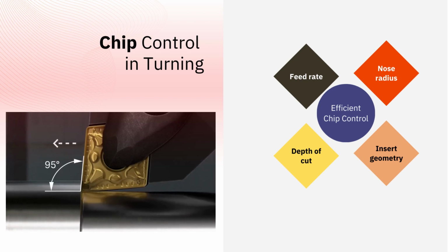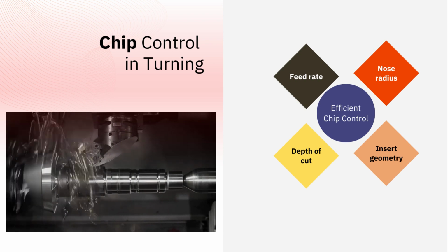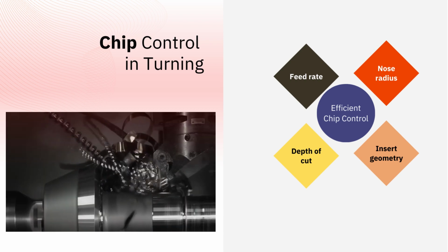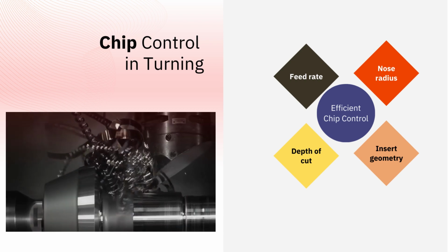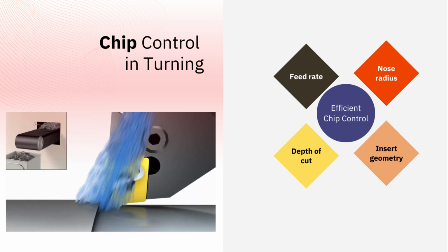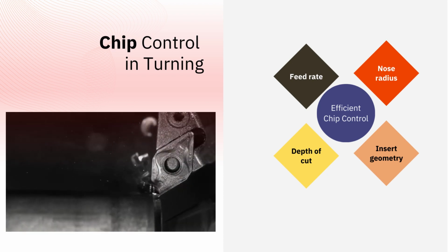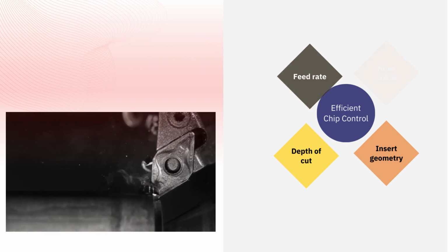Chip formation during machining negatively affects worker and tool safety, workpiece quality, tool life, and energy consumption, while also reducing operational efficiency. To alleviate such problems, continuous chip formation during machining must be controlled through chip breaking.